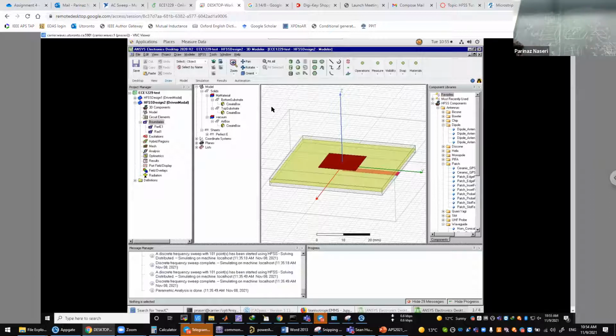So this is where the microstrip line is. This is where the ground layer is with some slot in it. This is where the patch is, like this, right? We want to go from the microstrip line to the ground. This is where the positive signal goes in, and this is where basically your zero is. So we define the lumped port, as we saw yesterday, in the same way, and then say that it goes from the microstrip line to the ground.